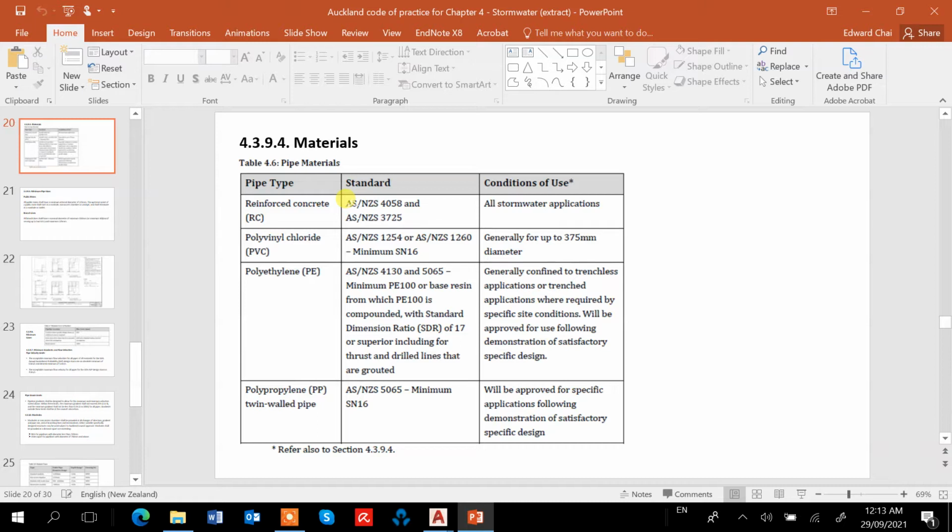So you just get it shipped. I think one piece of the precast concrete pipe is about 1.5 meters long. You bring it to the site and then join up together. So the PVC pipe, if you design for UPVC, that's UV resistant, can go up to 375 mm diameter. If we want to use the PE pipes, then we can go up to 450.